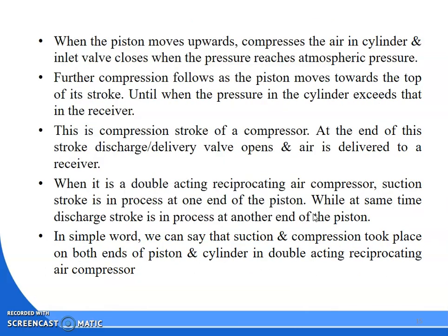And when the piston moves upward, it compresses the air in the cylinder. The inlet valve will be closed when the pressure reaches above atmospheric pressure. Then it will be sent to the what? From the discharge valve, it will be sent to the receiver. Okay. So what happens in the double acting cylinder? In the double acting reciprocating air compressor, the suction stroke is in process at one end and compression at the other end.